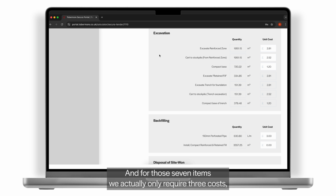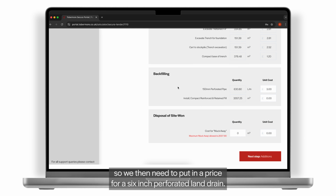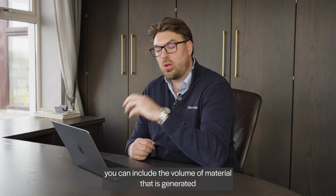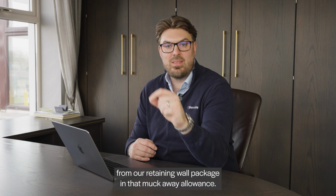And for those 7 items, we actually only require 3 costs, which is one for bulk excavation, carting of the material, and the compaction of the base. When you put those 3 items in, it will pre-populate the items further down for you. Within the earthworks, we then need to worry about our backfilling. So we then need to put in a price for a 6-inch perforated land drain. And we also need to put in the price for the installation and compaction of our backfill material. It then also allows you to include a cost for some muck away. So if you're in an excess of fill on the site and you're having to cart material away, you can include the volume of material that is generated from our retaining wall package in that muck away allowance.